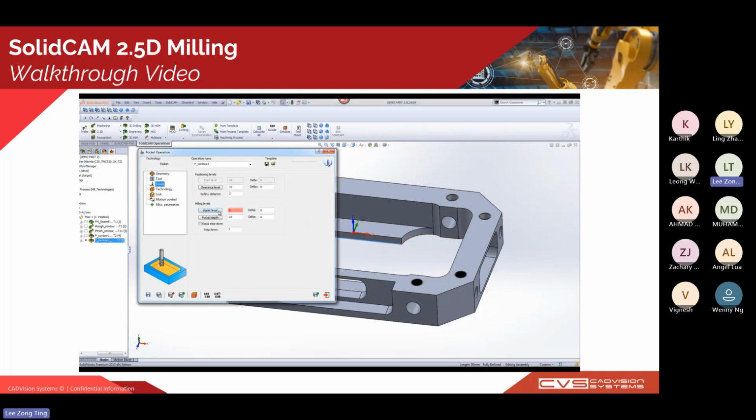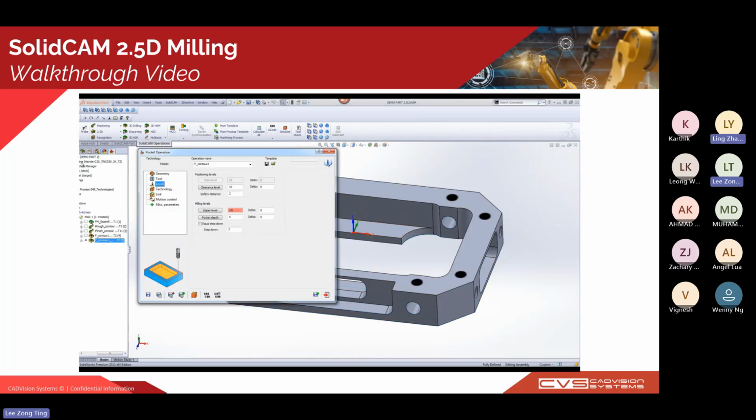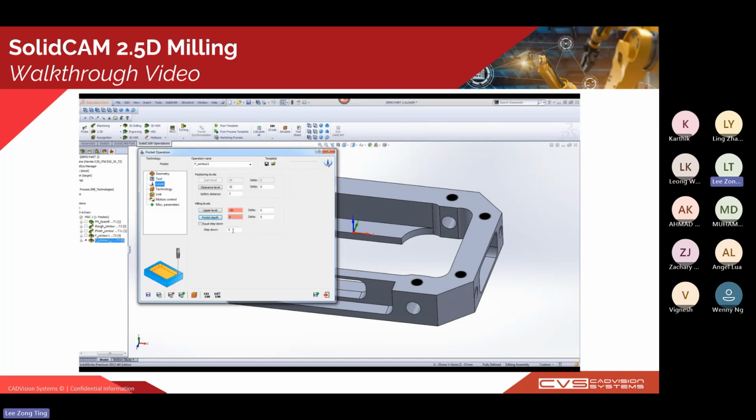And in here, we can do some minor changes, such as what I'm doing now, changing the geometries, and also I'm changing the pocket level. So the upper level will be another level, and I will change the pocket depth as well. So you can see how easily we are able to copy an operation we are satisfied with and use it on another pocket. We don't need to change too many parameters and re-input them again.